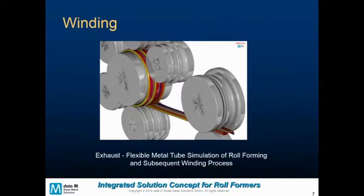We can also consider the winding process. So let's, for example, consider an exhaust tube, a flexible manifold, where the tube is roll formed in flat form, and then during the winding process it's interlocked. And this is quite an intricate roll forming process, quite often done in a few passes, with sometimes high strain at strip edge, and we can sometimes find ourselves using this strain to help close the profile, to help it interlock during the winding process. However, clearly doing this without simulation, on the shop floor, can take a lot of trial and error.